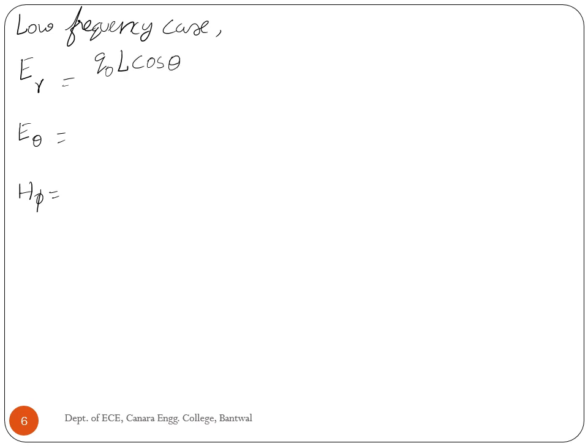In the low frequency case, we have three components, E_r, E theta and H phi. E_r is equal to Q0 L cos θ divided by 2π ε0 r³.